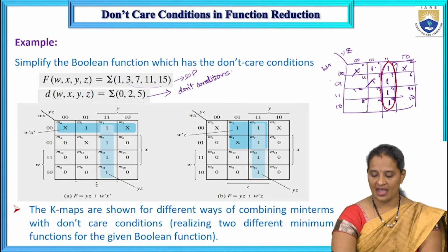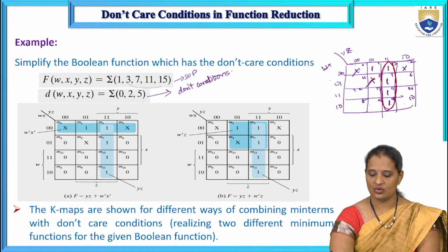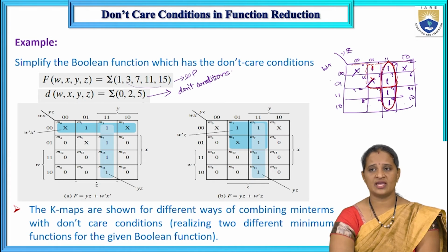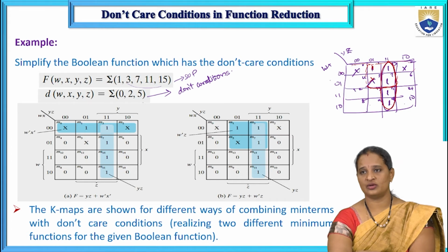As I told you, whenever it is needed, I can use a don't care. So I can form a group with these 4, and with these 4, I can cover this one. Is this group required? Not required, because all the ones have been covered. As I told you, it is not mandatory to cover all the don't cares.